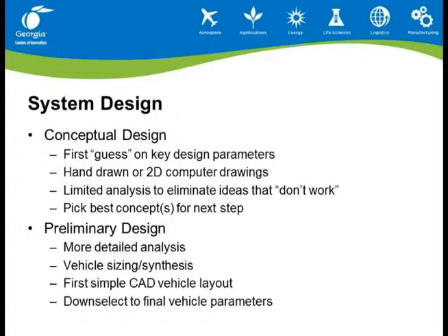which is preliminary design. In preliminary design, you do more detailed analysis. You start running the tools that were supplied through the Real-World Design Challenge. You do the vehicle sizing and synthesis. You first simple CAD, computer-aided design, vehicle layout. And then finally you down select to your final vehicle parameters when then you go do your detailed design. So we're going to talk mostly about concept and early preliminary design today.